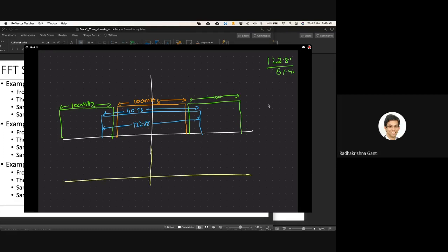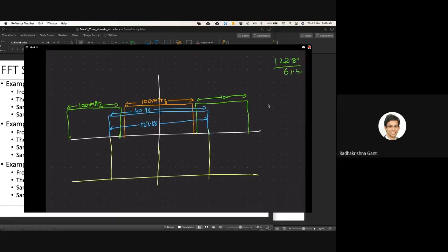So there are 4096 subcarriers corresponding to this point to this point. What you effectively do is, there are lots of subcarriers here. In all these subcarriers, you put zeros. First, let's talk about transmission. You always put zeros, a few more zeros here because of the guard band. And then your actual data will be in these subcarriers, 3276 subcarriers.